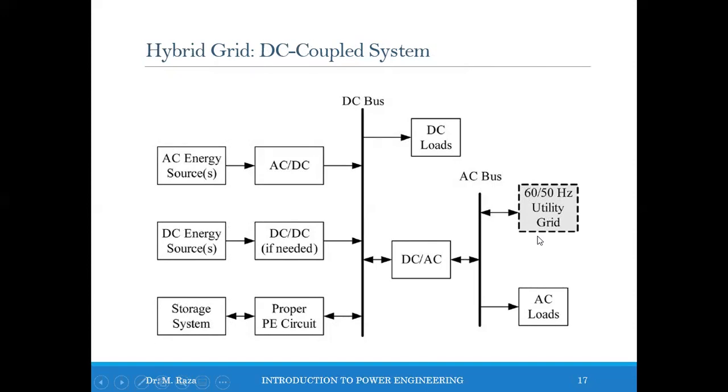To avoid this situation, it is possible to connect several inverters with lower power rating in parallel, in which case synchronization of the output voltage of the different inverters, or synchronization with the grid if the system is grid connected, is needed. A proper power sharing control scheme is also required to achieve a desired load distribution among the different inverters.